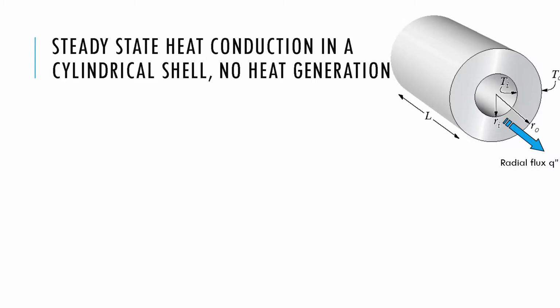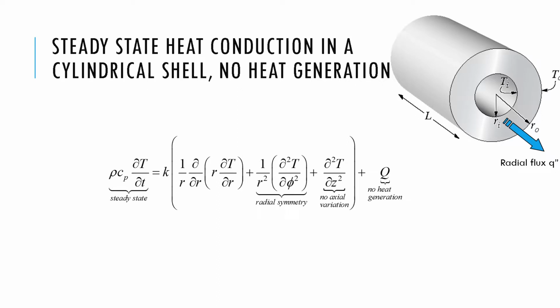Remember how we get started. We always get started with the most general equation. Now we already dropped out the convection term. Convection term has been dropped out already from this equation. So we have transient and conduction and generation term. But this is the most general governing equation. We have to now write the one that we need for our situation.